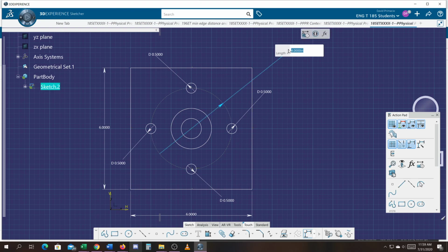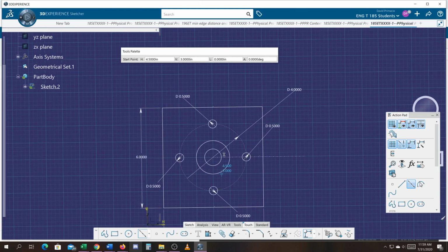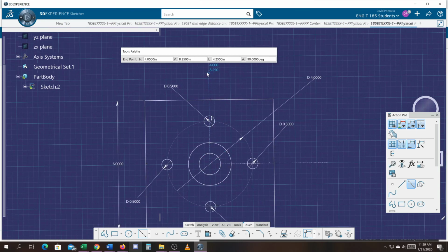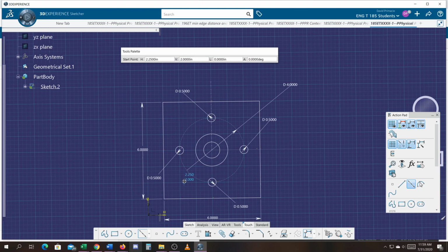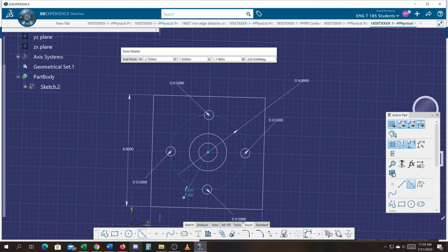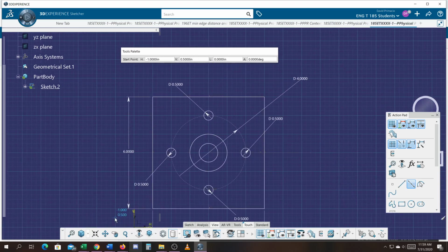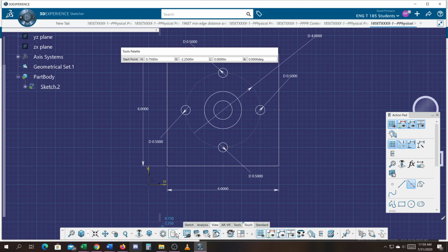And what I can do here is I can delete it. Or let's just leave it in here. I'm going to try and auto constrain this now. I got to put my axes in there, so we do it like I did last time. Now, when you do an auto constraint, the first thing it does is it looks to do coincidences, concentricity. It does all the geometrical constraints first. So I will put that flat to the screen here. Whoops. I'm going to auto constrain.